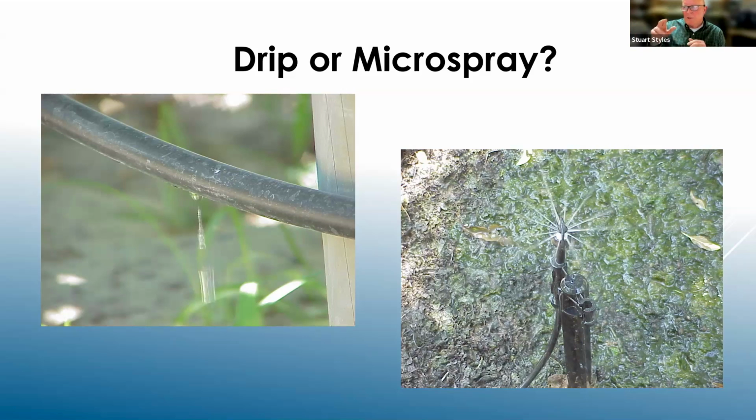What was happening is the water was trying to go down, but it wasn't going down. It was sealing up the top part of the soil surface. The problem was a chemical reaction from using really pure water, the very pure Friant Canal water. It had low salts in it, and the hydrogen ions would replace the calcium ions on the CEC sites, the cation exchange sites, and cause plating to occur. So the water wouldn't penetrate anymore; it would have to go out and then go down.